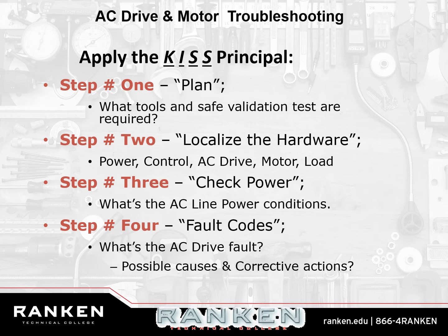Some codes can be really ambiguous though, and we're going to talk about that when we get in the shop, because you'll get a code that says an overvolt. Well, overvolt can mean 100 different things. It could have just saw it for a split second and now it's gone. It could have been those reflective waves we talked about yesterday.